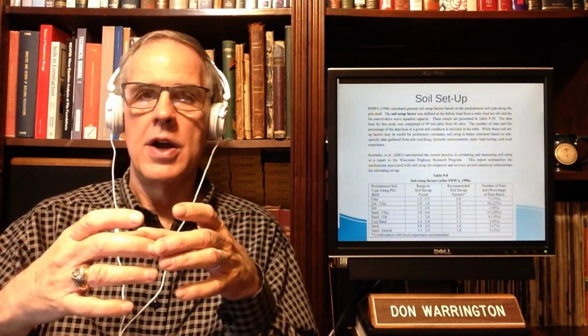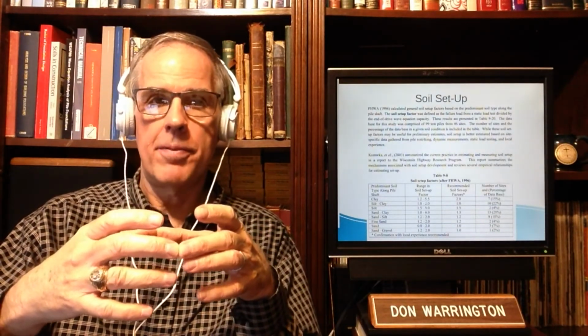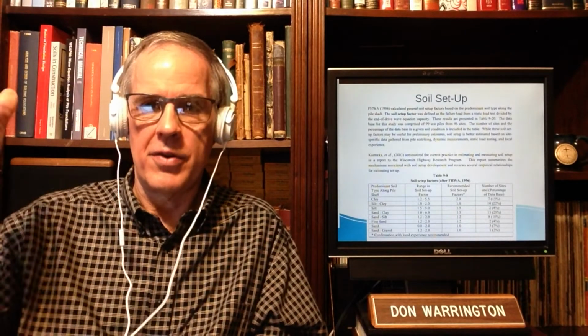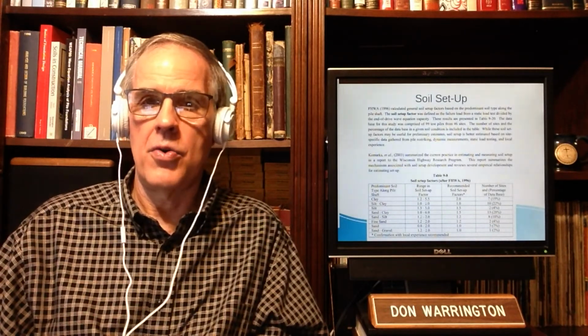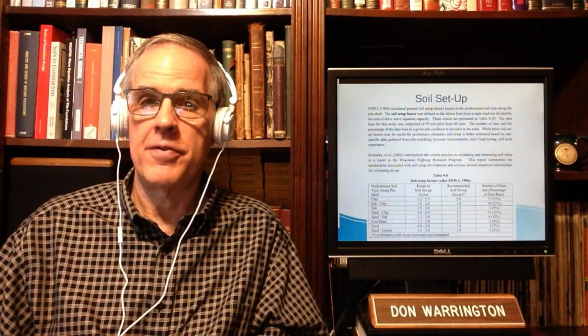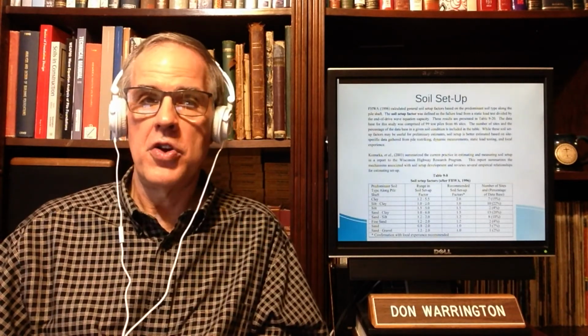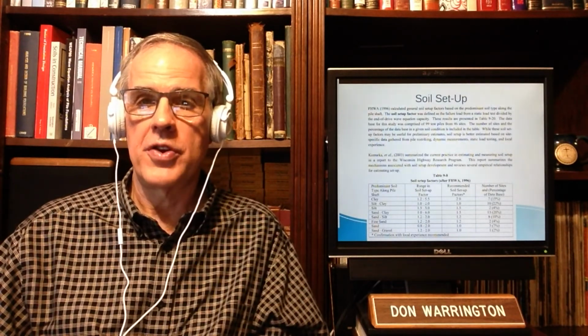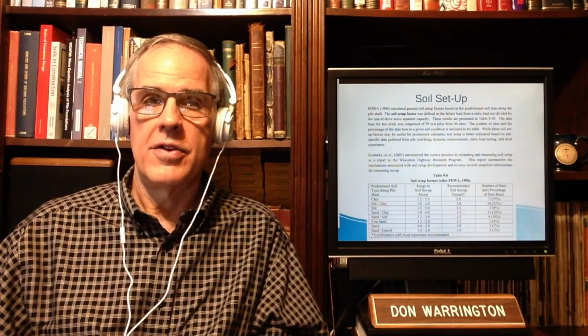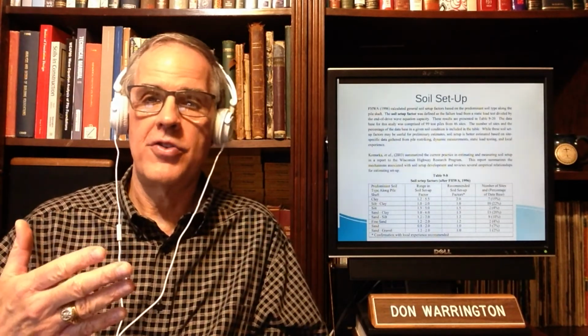Well, what happens in a pile is basically a consolidation around the pile, where over time, after the pile is driven, the pore water will dissipate. Because of the way in which it's loaded, in other words, it's loaded in shear, and remember, for those of you who take fluid mechanics lab with me, a true fluid is one that at static either deforms continually on shear or doesn't take the shear.